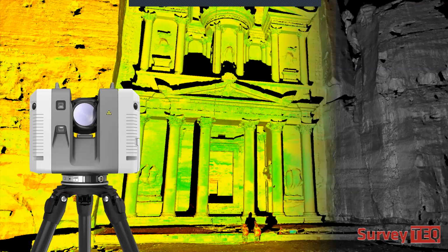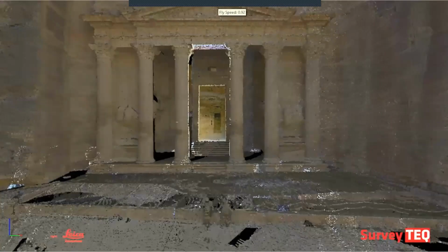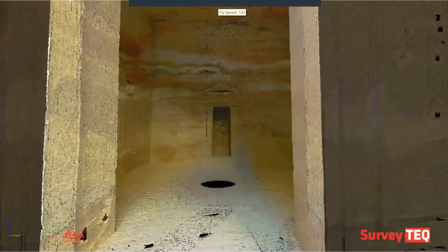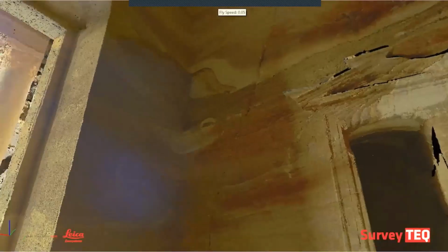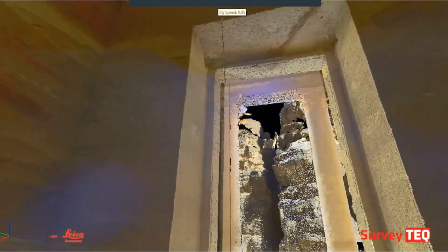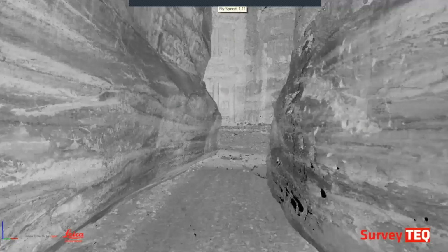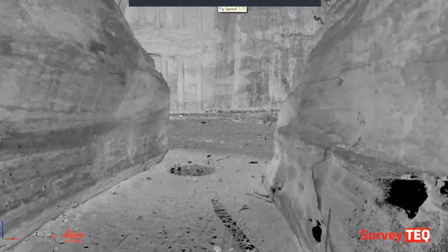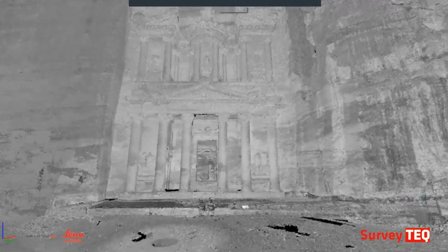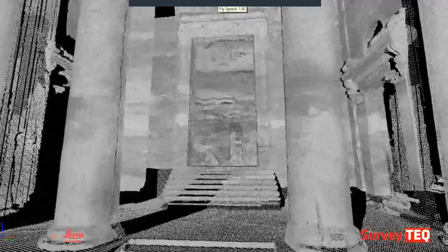and it was digitalized from a real structure to a digital structure. Post that, this digital structure was analyzed for how it looks, what the dimensions are, and all the structures inside and outside the building, when you look at the dimensions as well as how it looks in all 360, so that if you want to replicate a model of this, or you want the right dimensions for refabrication, you can get the most accurate analysis. You can even understand how narrow the spaces are, how you can put up the buildings, how you can bring machinery to work in these particular environments, and what kind of damage will happen if you do something wrong. So in all those structures, to restore our heritage, we have used the RTC 360.